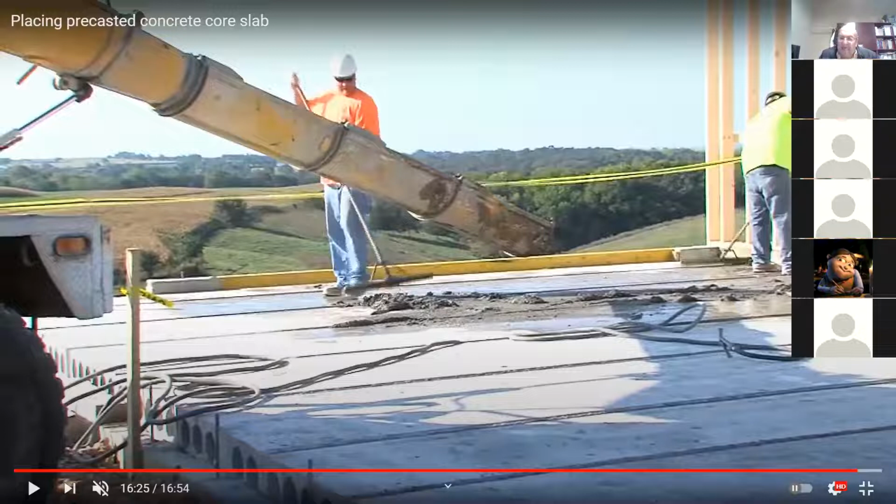After you do this, from one side you put the anchor. The anchor is like a connection that you put at one end. And then you have a jack, you come from the other side, and you start to pull the cable. So you see what happens? It's going to be post tension. It's after you pour the concrete. Now there is no good bond, or sometimes no bond at all, between the cable and the concrete.